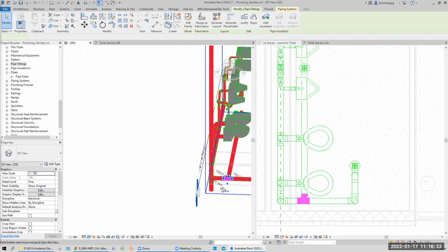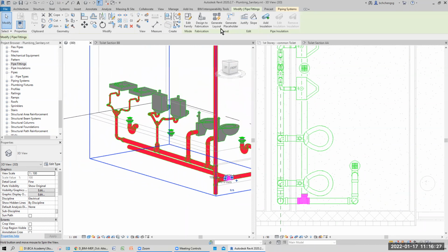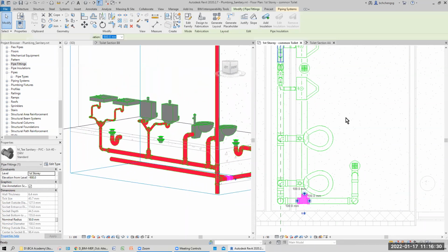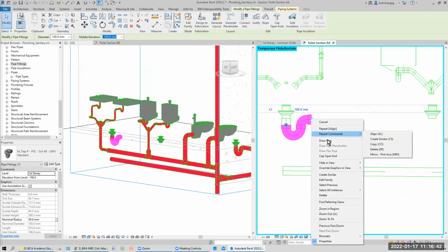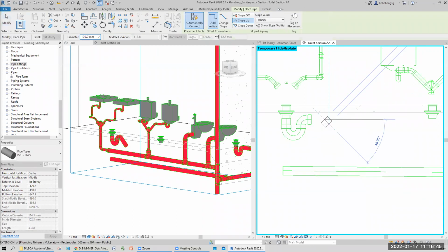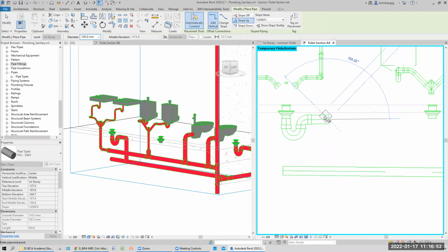Now it's time to get them connected. So to connect, you have to go to your section AA here. So draw, connect here. So connecting point, pipe, right click, draw pipes. So straight first, then vertically down, no sloping, remember. This one sloping is also wrong, so escape first.